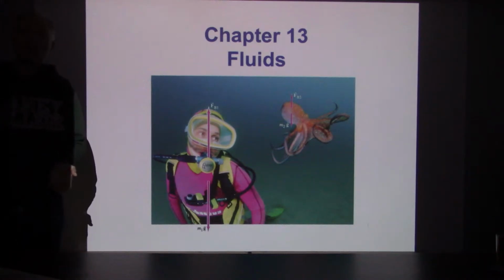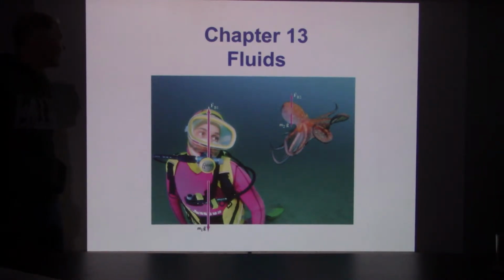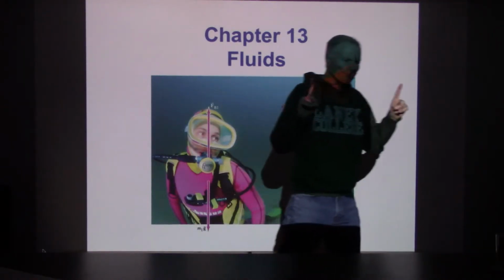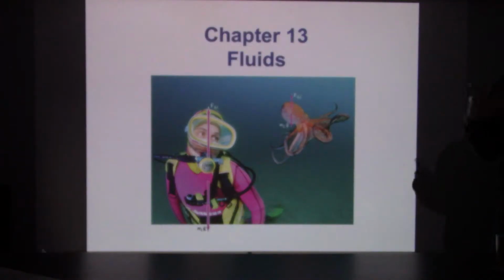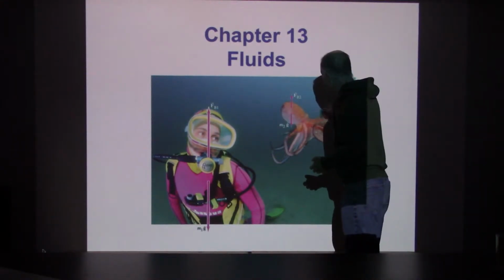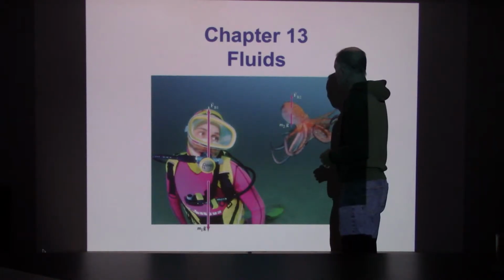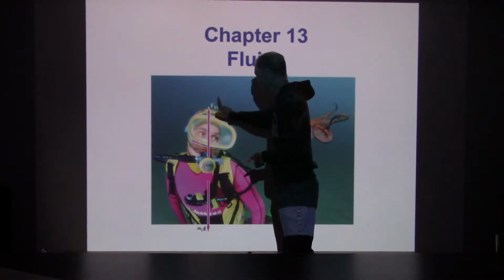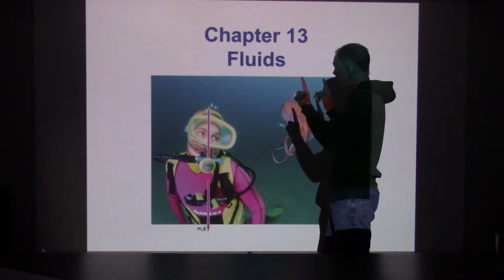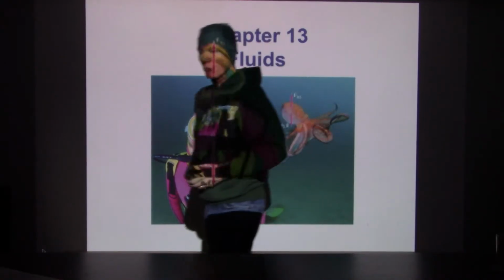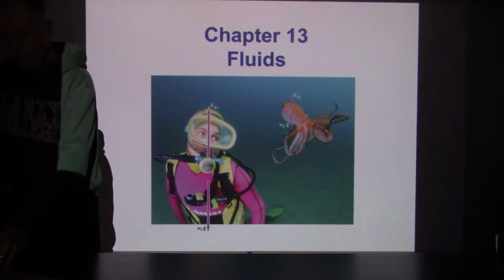So one of the most remarkable things we run into with fluids is that you can float things, right? Or in the case, even if something is submerged, there is this upward force we refer to as buoyant force, and we're going to spend a good amount of time looking at that. But that's an interesting effect. Because of the way that the fluid pressure is working, we end up with a net upward force. So the scuba diver has an upward buoyant force as well as a gravitational force. Okay, and that's what some of the force diagrams are going to look like in this chapter.